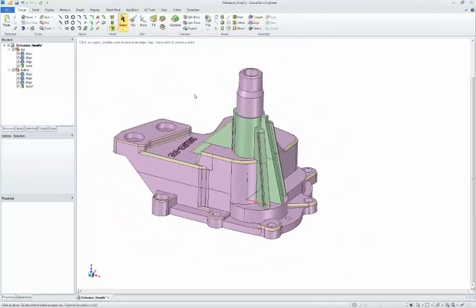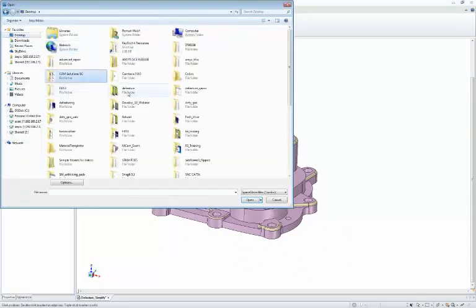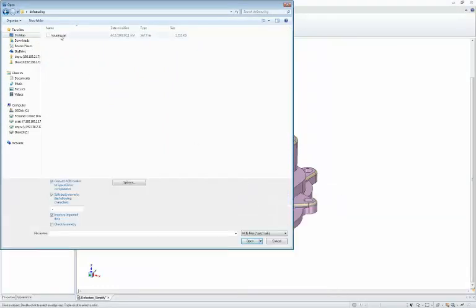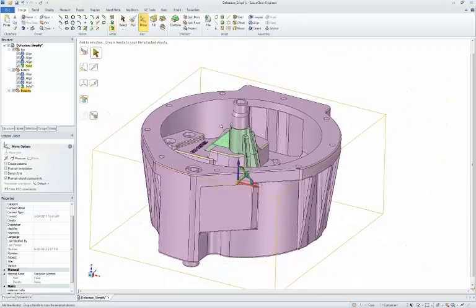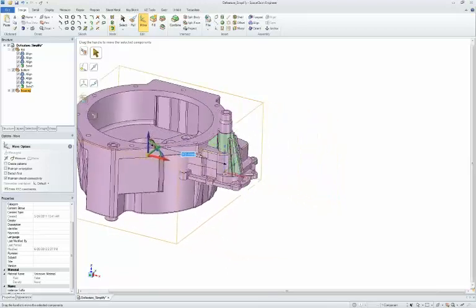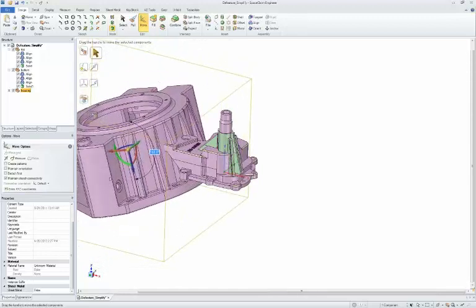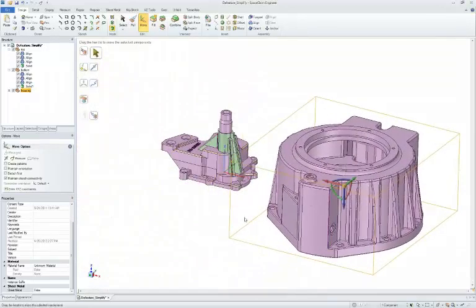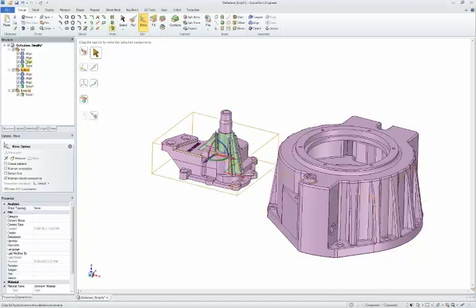I could have also created an assembly, though, by inserting a file. If I insert a second file, like let's say I inserted that ACES file into this design, I can bring that housing into this nose cone assembly. So now I have this part that I just brought in also in my design that I'm working on and using. So again, there's a lot of ways that you can start to bring in different parts and models and assemblies into one design to start to create an assembly. So now we have three parts. We have our housing, we have the top and the bottom of this.